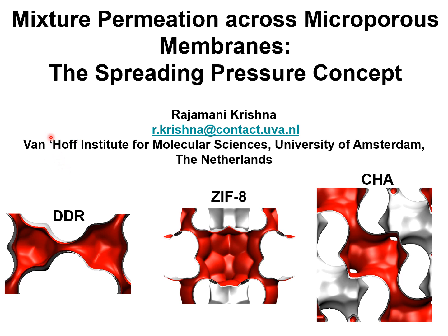The objective of this presentation is to gain fundamental insights into the mixture permeation characteristics of microporous membranes. Specifically, we underscore the importance of using the spreading pressure concept to describe mixture permeation across microporous membranes constructed, say, of layers of DDR zeolite, ZIF-8, or chabazite.